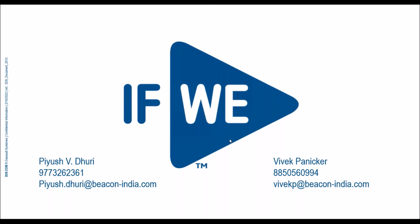What all 3D modeling software can export 3D models for analysis? All the desktop-oriented software which is installed on the desktop, or where you can create the modeling, can be connected with the current tool, that is the SIMULIA tool. Or else you can convert those files into a neutral file like a STEP, IGS or Parasolid, and then import it in our particular tool.